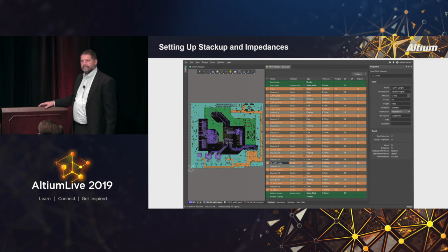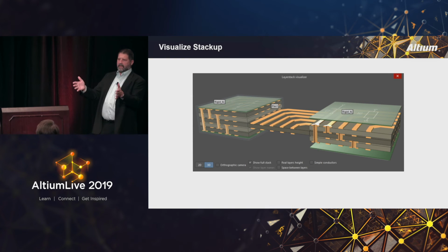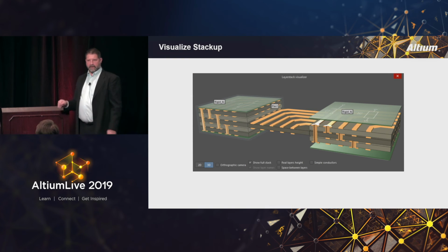With an antenna, don't you want it to have no reference in the board? Well, the antenna itself, I think you're talking about the feed line. The feed line, yeah. From your part to the antenna connector. Yeah, you can have a wider trace if you reference to a layer that's farther away.